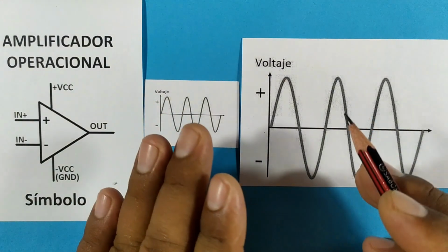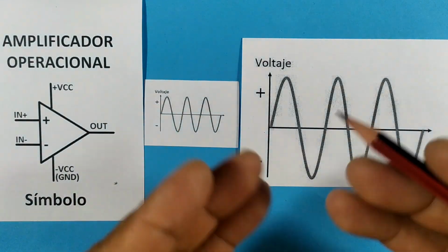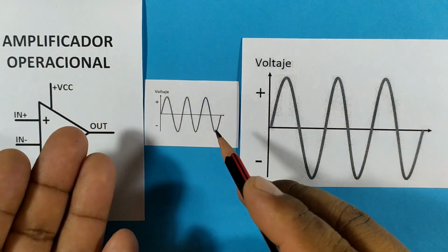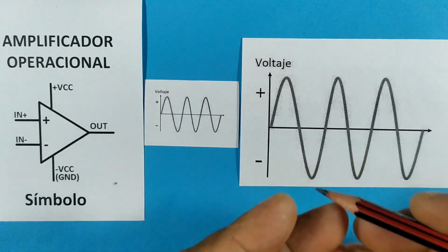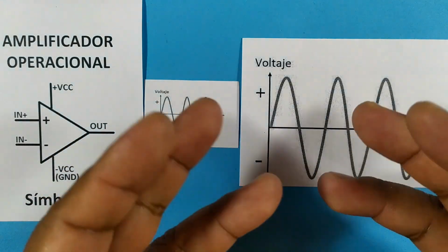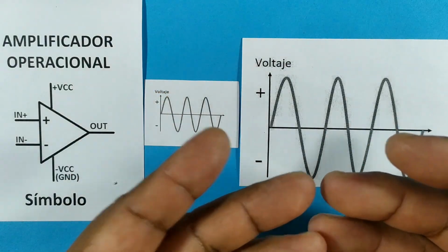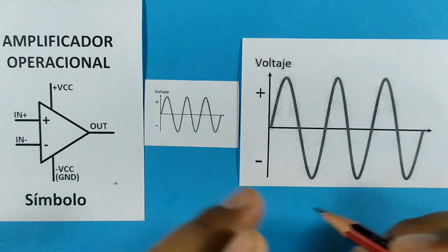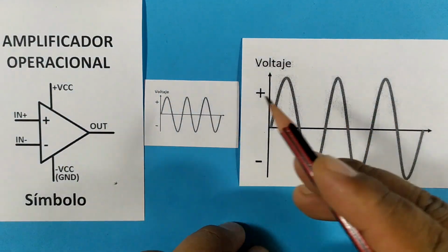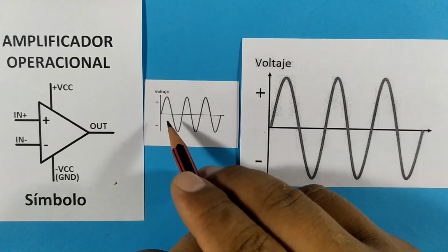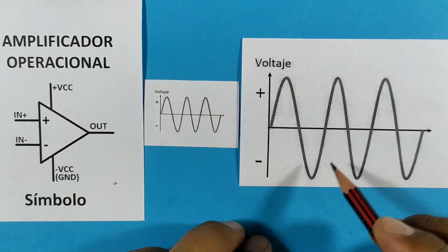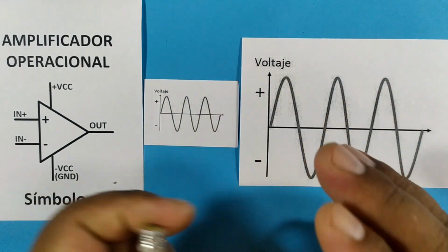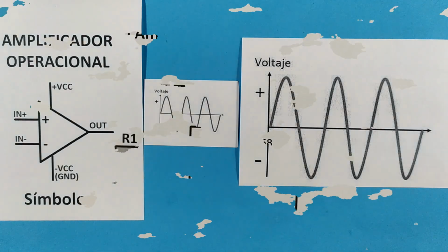In essence, an operational amplifier can amplify up to 100,000 times according to the data sheet. That is, if they have 1 millivolt, they can amplify it 100,000 times, and that will be a fairly large value. But it never reaches those extreme values, maybe about 1,000 times or 100 times. Usually a value less than the maximum. Therefore, what the amplifier will do is preserve the shape of the signal by amplifying it at higher voltage levels. The same is how transistors work as audio amplifiers.